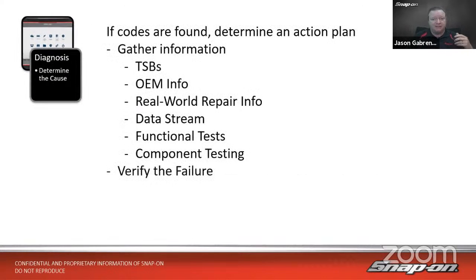So last time, as I said, we walked through the diagnosis portion, right? So to catch you up, we went through gathering our information, right? This vehicle had two codes in there. We had a misfire code and an evap code. So we walked through the TSBs first, and lo and behold, we had two TSBs for our P0300 misfire code, and the information in that TSB actually helped us fix that problem with the vehicle. It was a missing clip on a spark plug wire. After that, we switched over because that solved that problem, but we also had that evap code, the P0446.